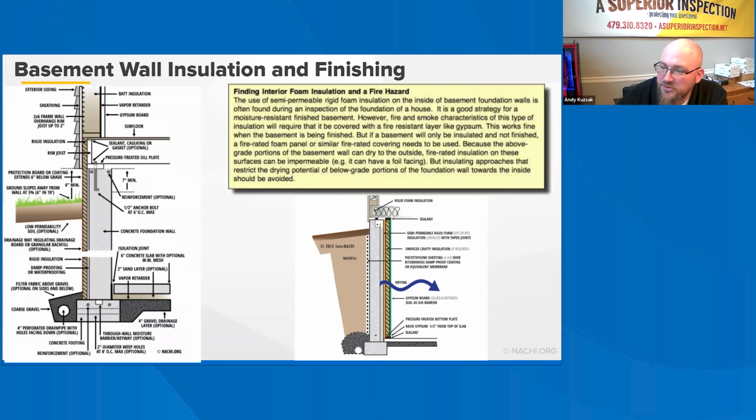Gypsum wallboard, wood trim, and wood framing wick moisture from the slab, cooling materials in contact and creating higher surface humidity levels, potentially supporting mold growth. Finishes and baseboard trim should be held a ½ inch above the slab surface, sealing gaps with caulk or sealant to prevent indoor air leakage into the wall assembly. A thin foam plastic sill sealer may be used underneath the finished wall's bottom plate for added moisture protection. During basement inspections, check the bottom of the finished wall for moisture.